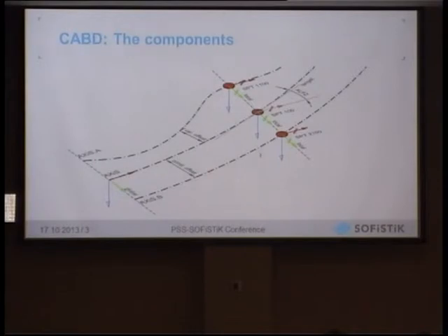dependent elements. And if we think about, we want to model a transverse girder at one of the support conditions or one of the support situations, we need to go through a really complex process of sine, cosine, tangent operations in order to arrive at our points, which might be easily described like this. You are at the bridge axis, station 30 meters.